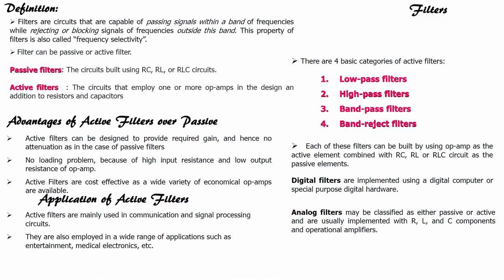Now, what are the advantages of active filters over passive filters? So, active filters can be designed to provide gain and hence no attenuation as in the case of passive filters. We have seen that in the earlier course. Same way, there is no loading problem and active filters are cost effective.